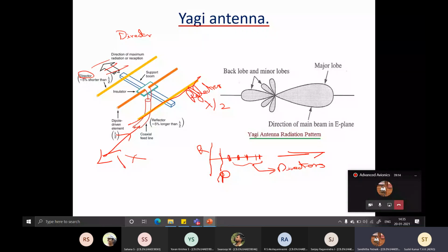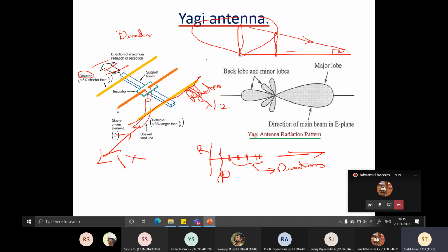Marker beacon, sir. Good. Because let us say this is the touchdown and you're landing like this. Marker beacons are just at a single point, and you want these beams to go up. You don't want it to flare up like this, right? You don't want a radiation pattern like this. You want a very narrow beam to be generated. So all these marker beacons will be using Yagi-Uda antennas. Okay, good.